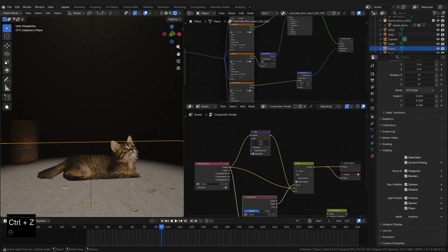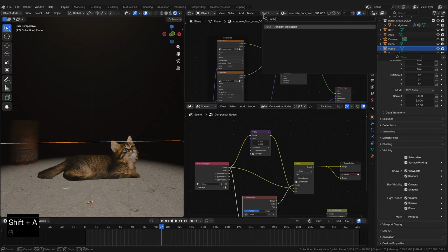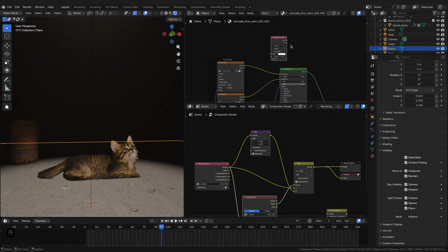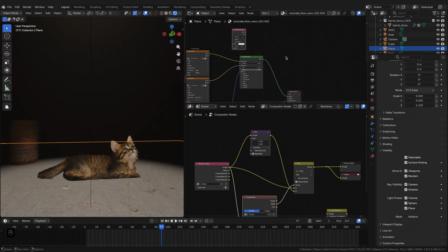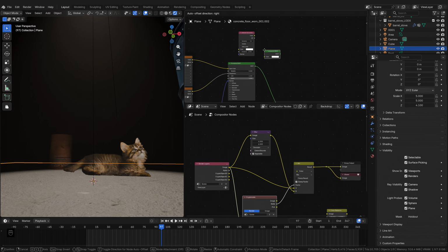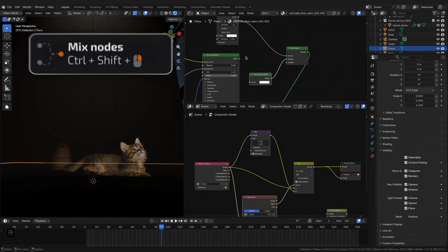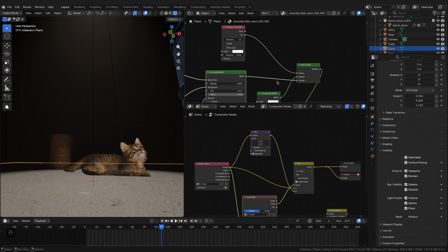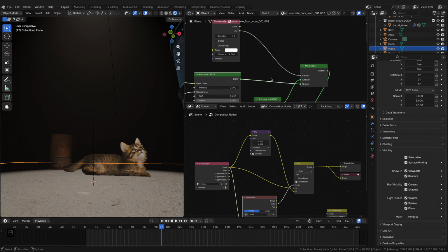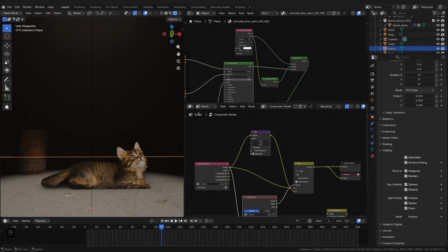Since we want the shadow to be casted onto the ground, we will have to edit the shader of the ground. For this, we will use an ambient occlusion node, which will create a black and white gradient everywhere other objects are touching the ground. Then, to actually get the shadow, we will just add a transparent BSDF node and use a mix shader node to combine it with the principled BSDF. Put the transparent BSDF into the top shader input, the principled BSDF into the bottom input, and then connect the AO output to the vector of it and to the color input of the transparent BSDF.